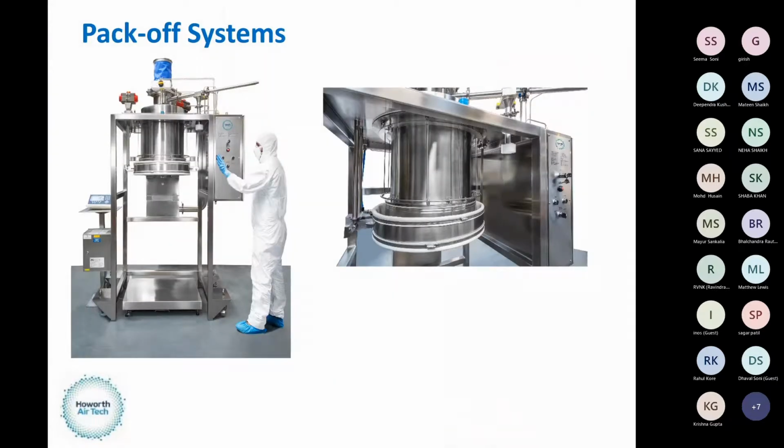And then the pack-off systems, again, these are quite common in the manufacturing areas where you're coming from a filter dryer or a centrifuge. So we're packing off using the continuous liner system. So we have an inner bag and an outer bag. So again, this gives us a contained solution using the continuous liner methodology to pack off those powders.